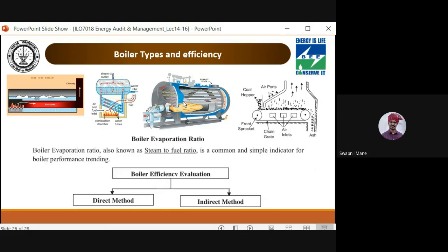Packaged boiler. The third diagram is a packaged boiler in which you see the fire is there at the bottom. It is surrounded by a tank with water, and also we have the tubes which will carry the heat. So you see this is called the flame. So flame propagation, this is also engineering required for how the flame propagates in a boiler. There should be a fan, there should be a blower, there should be a pump for feeding the water. So all these are boiler accessories.